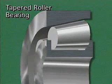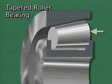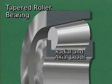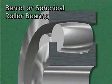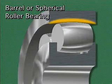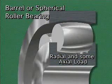Another type of roller bearing is a tapered roller bearing. In tapered roller bearings, the rollers are smaller at one end than at the other. The rings are tapered to match the rollers. Tapered roller bearings can support both radial loads and axial loads. Barrel or spherical roller bearings are self-aligning bearings. The outer ring is shaped like part of a sphere, which allows the bearing to align itself. Barrel roller bearings are designed to handle primarily radial loads, but they can also handle some axial loads.